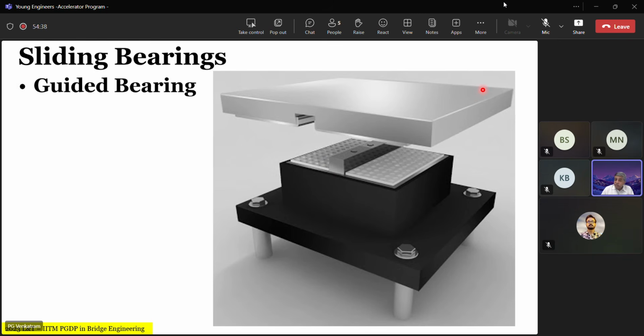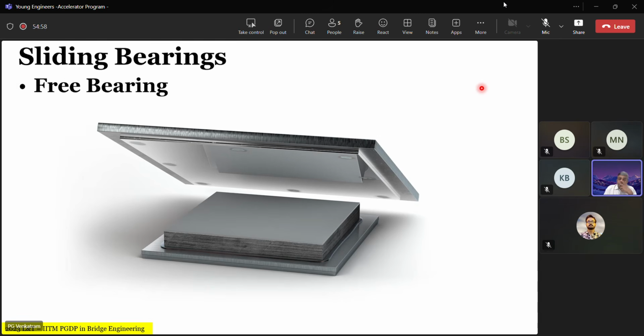So these are ways in which different types of elastomeric bearing each lead to a certain boundary condition, which you must remember when you choose the type of bearing when you're doing your modeling, so that the boundary condition connection between superstructure and substructure is properly input with the relevant degrees of freedom as you decided. Okay, going back to repeat: you saw only the PTFE sheet. Now this is a PTFE sheet with the sliding stainless steel on the top plates. This will permit movement in both directions.